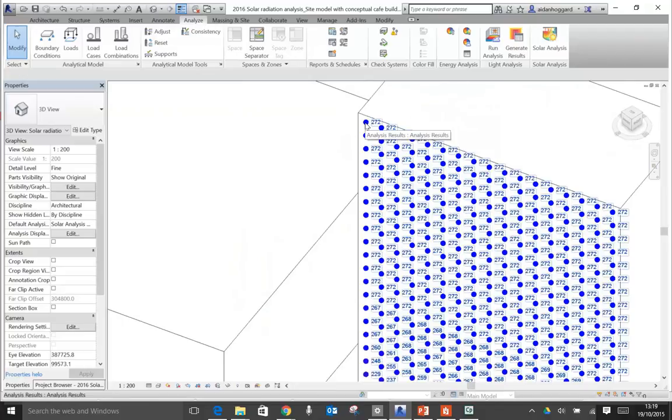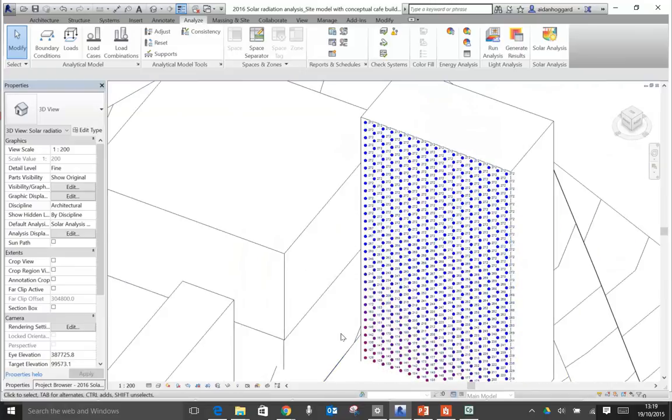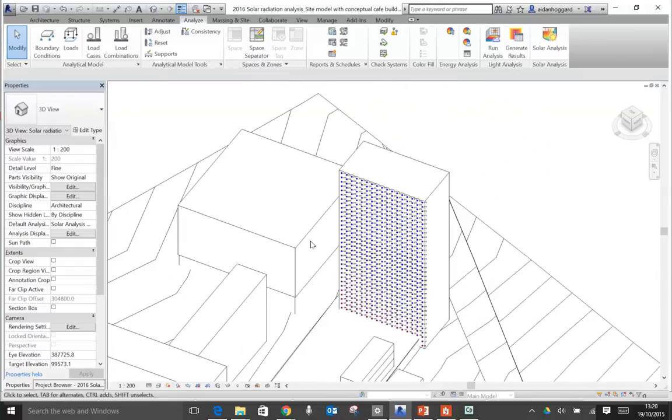So we've got double the amount of energy and daylight at the top of the Arts Tower as the base, and you might not expect that necessarily. And as we've discussed before, this is why building facades should probably vary across the facade, because the energy levels are very different.